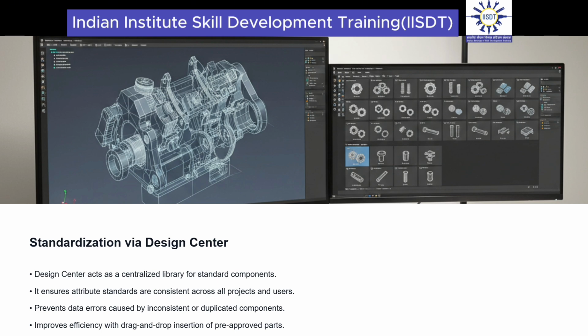Think of the Design Center as your company's official, centralized library for all approved CAD assets. Here you store your standardized blocks, each one meticulously created with the correct geometry on the right layers and, most importantly, with a full set of predefined, accurate attributes. Whenever a designer needs a component, they don't create it from scratch. They simply open the Design Center, navigate to the correct library, and drag and drop the approved block into their drawing. This simple action has profound implications for data integrity.